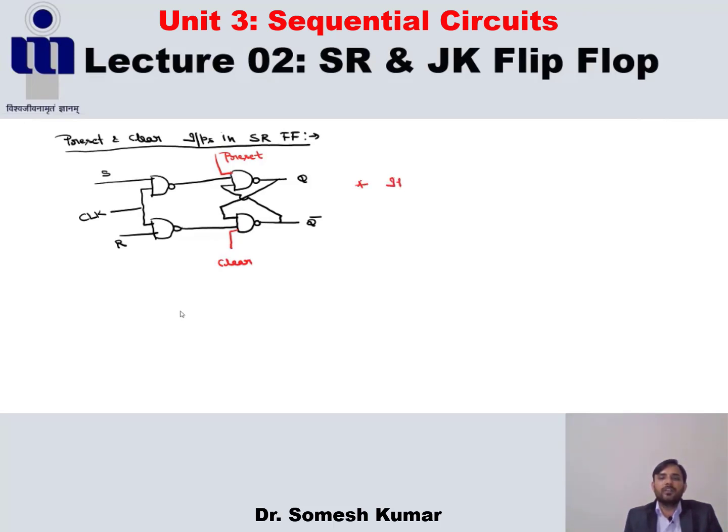The first case is if this preset pin is 0. Then what happens? You know, in a NAND gate, if any input is 0, then the output of this NAND gate becomes 1. That's why we are saying this is the preset, which means if this preset pin is 0, then it automatically sets the output to 1.